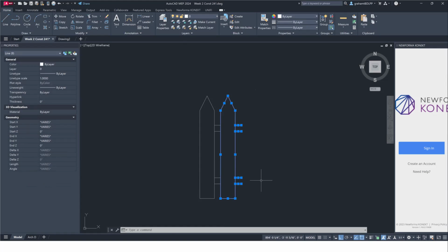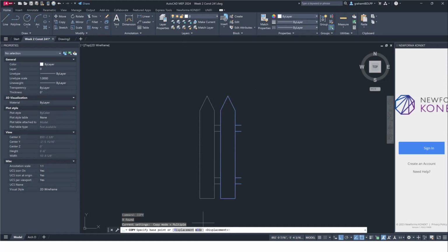And what that's going to do is it's going to take a fence post and keep adding 1 to the right of every place that I copy and paste to. So I'm going to use my copy command, COPY, enter. I'm going to choose the bottom left corner. I could choose the top corner, top here. It doesn't matter what point I choose. The important part is that I click that exact same point every time on the next copy over.